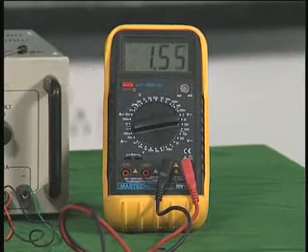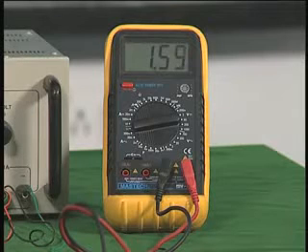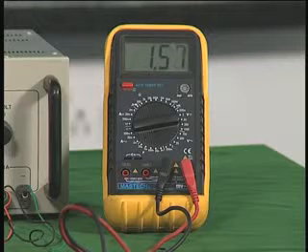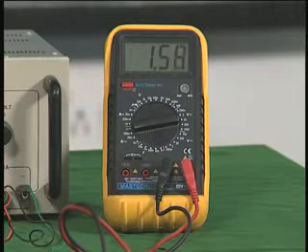Previously if you remember, when I changed from 100 to 200, 300 millivolt, it was changing from 0.48 to 0.51, 0.53, it was changing very slowly the output compared to the input. Now what is happening, for a change in input there will be a very large change in the output, exponential increase in the output, because it is an anti-logarithmic amplifier.